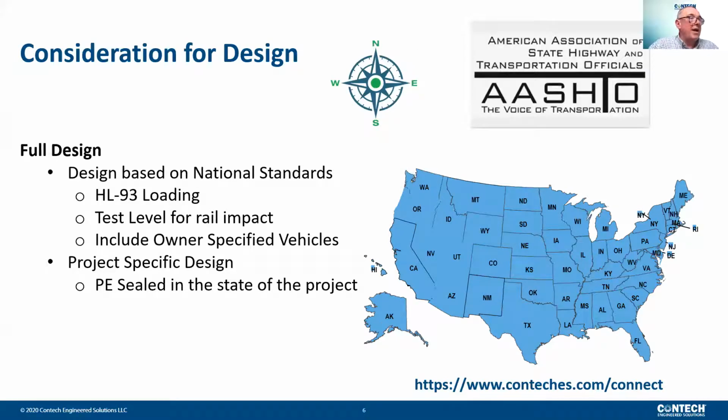When considering any bridge option, design is key to a successful project. Following AASHTO National Standard LRFD design methodology using current HL93 loading, as well as owner-specified vehicles, you're confident that the bridge will meet its site-specific loading needs. Incorporating test-level guardrail, also meeting AASHTO standards, shows consideration for this design element, not leaving it to an arbitrary choice based on what someone may think is sufficient.